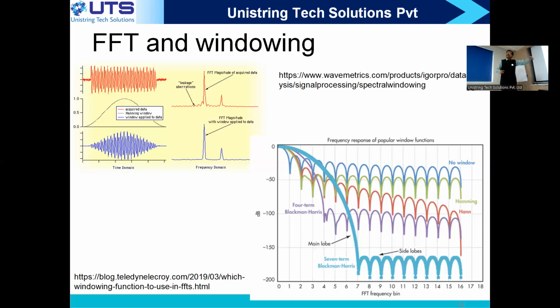So I give away certain things: I'm letting this peak broaden a little, but I'm able to suppress very little. Whereas if you choose another window function, let's say 4-term Blackman-Harris, I'm able to achieve around minus 90 dB side lobe level. But it is able to restrict its energy up to only the 4th bin.